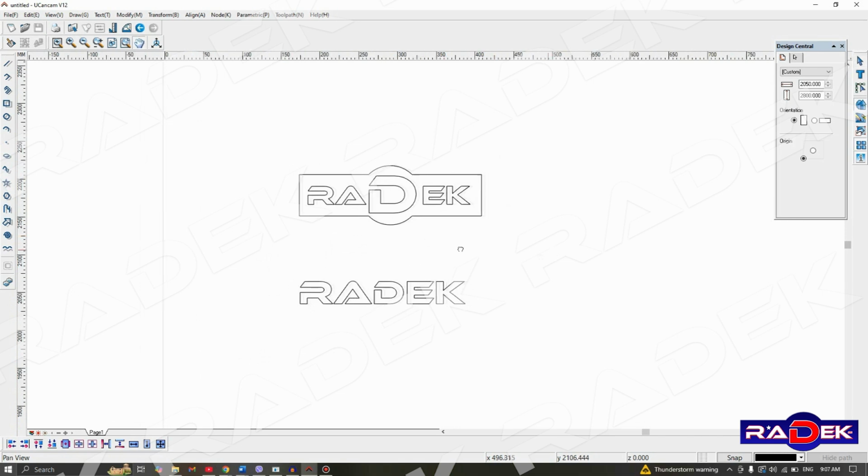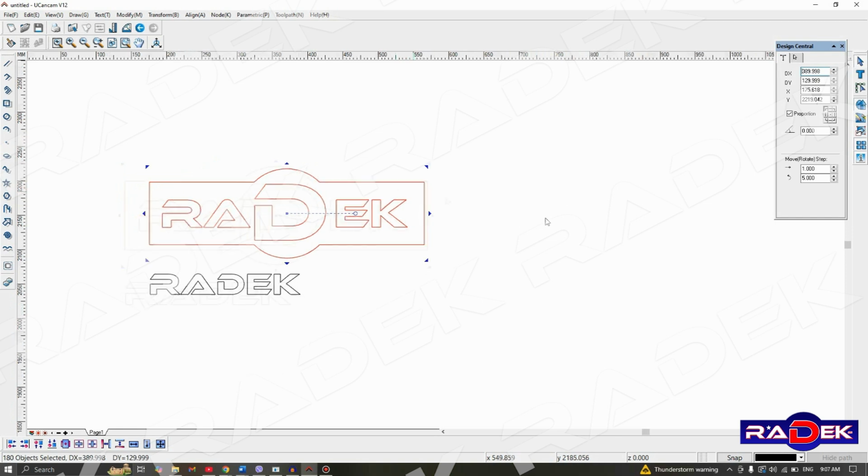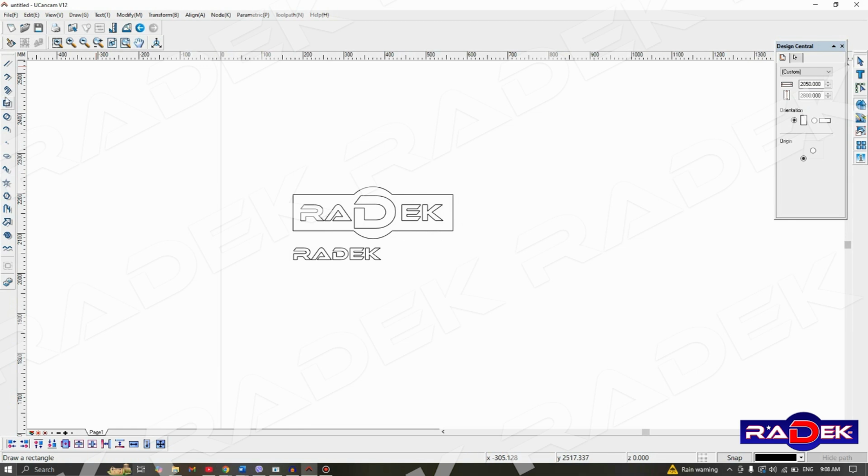What I want to do with this project is to manufacture a tabletop sign built in two separate elements, the sign and the stand for it. First thing I'm going to do is to create the stand. I will draw a rectangle, and in the window Design Central we can notice some additional options which enable us to choose the type of corners for a rectangle. We can choose between regular rectangle, fillet rectangle and chamfer rectangle. I will select the option fillet rectangle and complete the drawing.